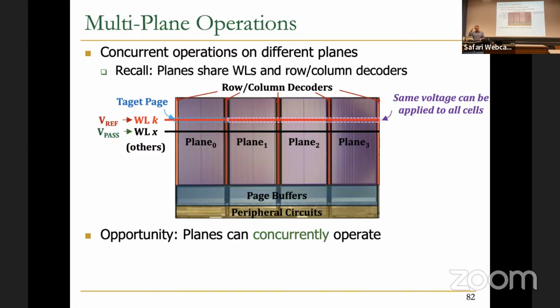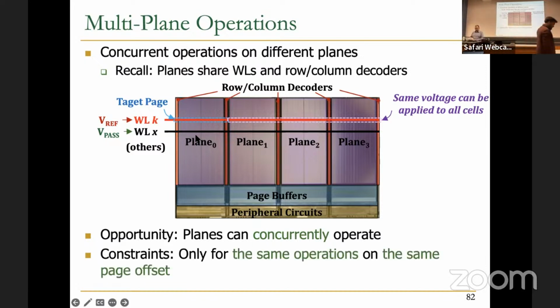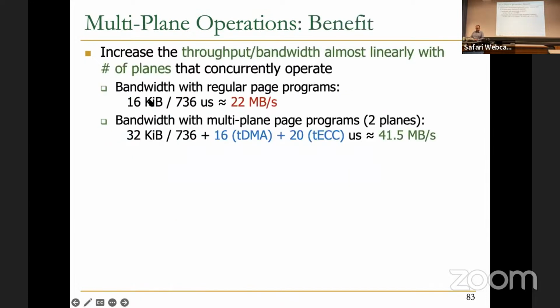Okay, so this is multi-plane. As long as the offset is the same, you can use it, and you can operate concurrently. So with multiplane operations, as I said, you can overlap sensing and program latency, depending on whether you're doing multiplane read or write.